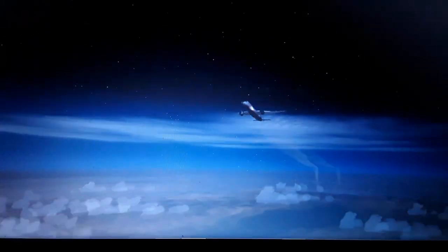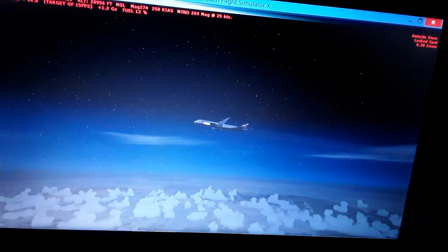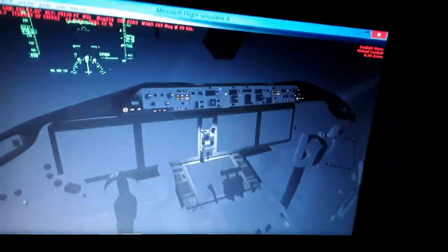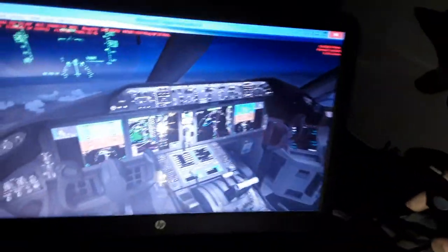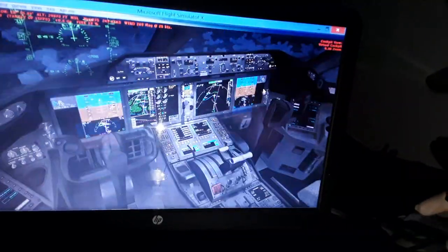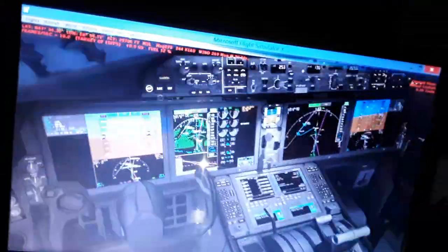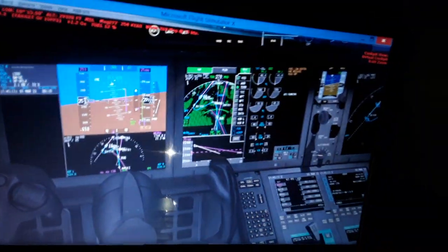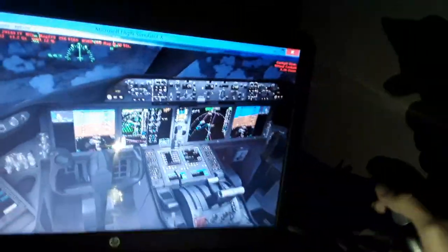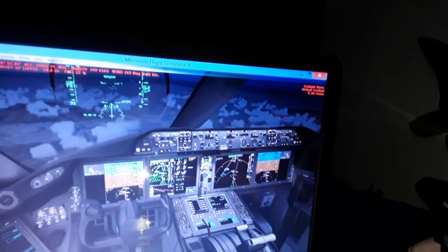And we need 8 more minutes to go back to the airport, so we may start now the descent. So we use idle thrust like this. Idle thrust. And pitch down the airplane. Keep flying manually. And we have 7 more minutes for this flight.